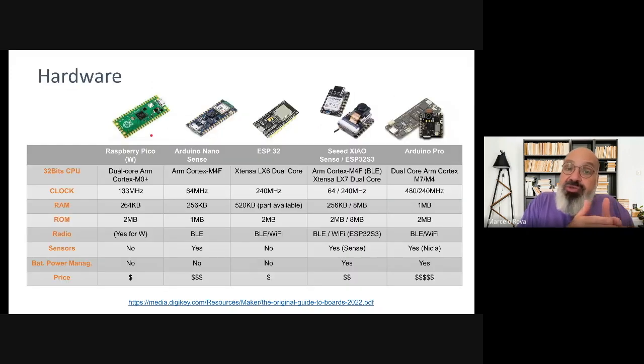But because those are development boards, they have more than the microcontroller unit. You'll find in almost all of those boards some kind of interface to connect with your computer, and some kind of power regulation to receive 5 volts, for example, and convert to 3.3 volts. That's most common in this kind of PCB.